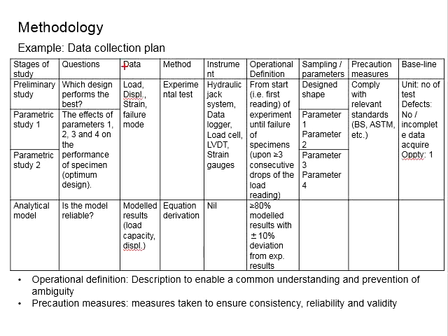You need to determine what kind of data you intend to collect from the experiments. Let's say now in this case, you are testing a beam. You would like to know the load acting onto the beam, the displacement as measured from the deflections of the beam, the strain of the reinforcement bar, as well as the failure modes of the beam. Knowing the data that you need to collect, then you have to decide the instruments to be used.